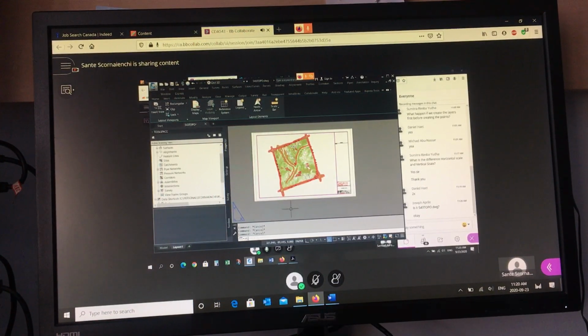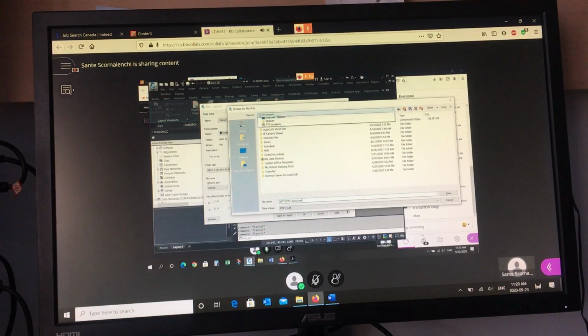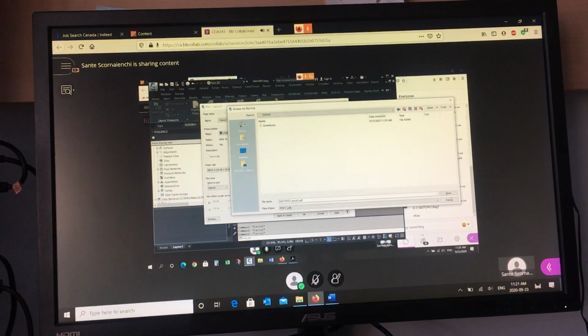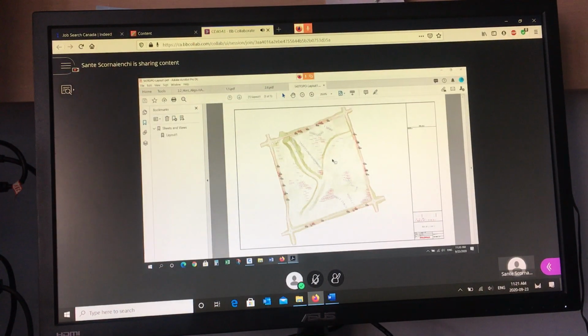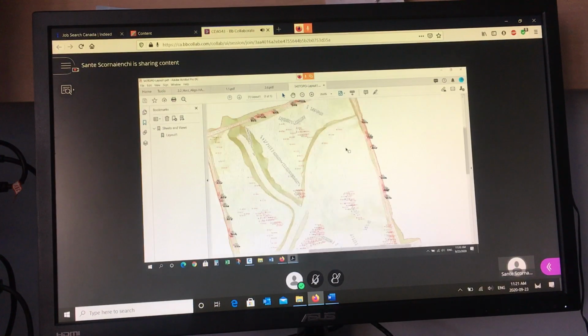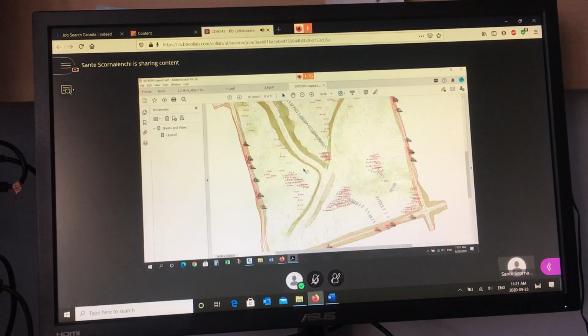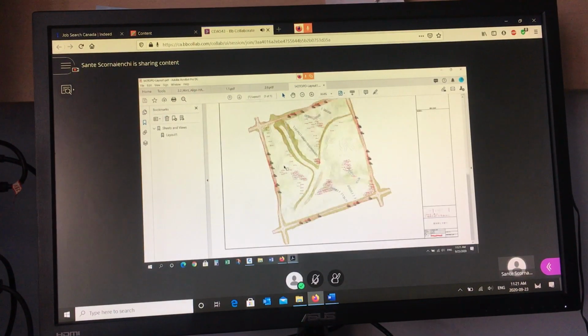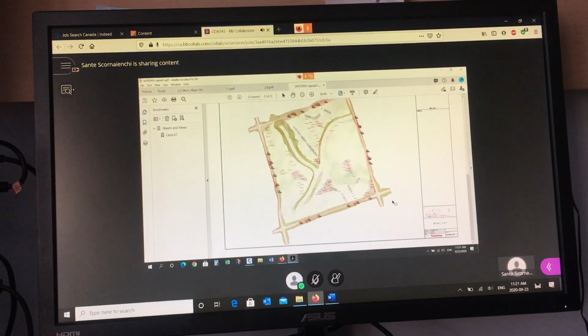And then plot it. And all you have to do is say, okay, it's ready to go, and save it somewhere. I'll put it on my desktop under the course code with all my drawings. And there's the PDF. Okay. Now it looks kind of light, but if you zoom in on it, all the color is there. It's all going to be fine. And I'll be able to mark the PDF. Right? I can just check to see that the appropriate layers are frozen or thawed, that you've got the right contour interval. And then I'll go into your digital file, I'll check the scale, I'll look at your title block information, make sure everything's there that should be, and so on.